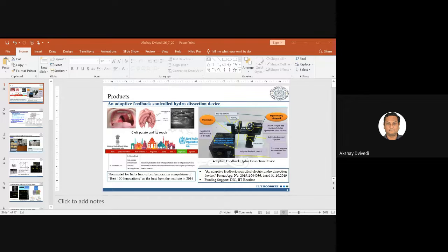Here, the tool texturing system that we developed earlier for usual electrochemical discharge machining, we use that same thing to develop a sort of roughness, or in fact a texture, on the wire surface. The end result: there was something which was required, and that was channelization of electrical energy, so it becomes distributed over the entire tool surface.